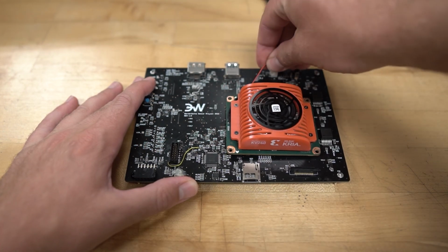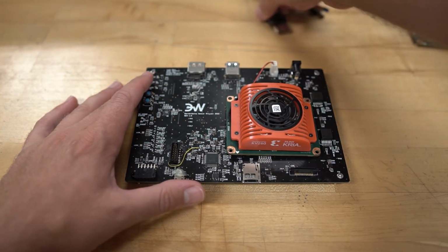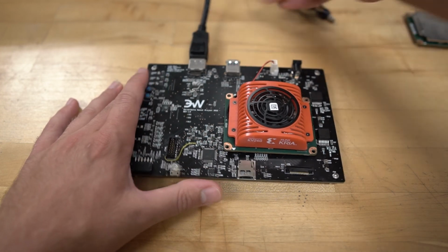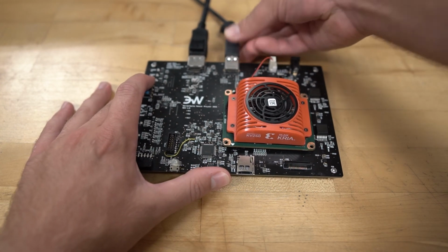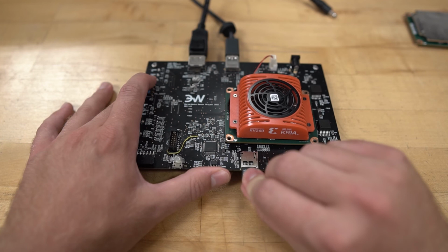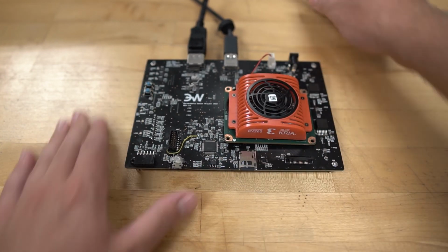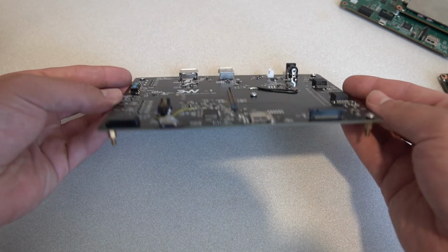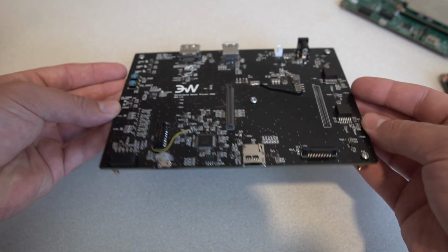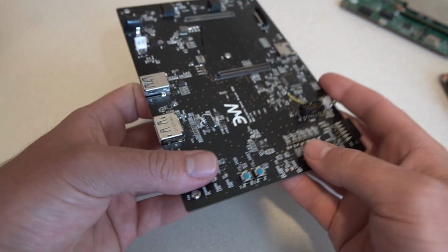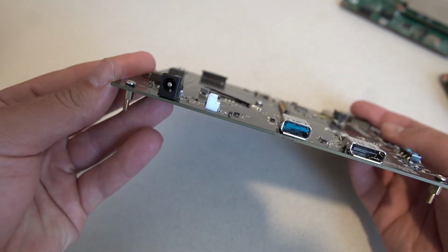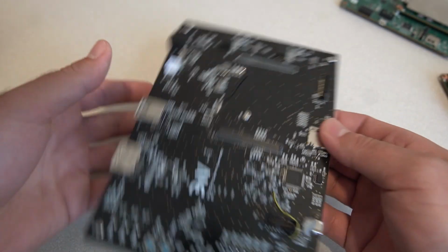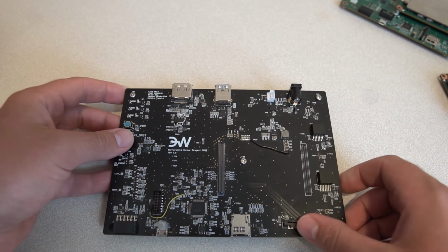On our own custom board here, all that we needed was the main connector here in the middle for our Kria SOM, which plugs right in. And then we have an SD card here on the bottom that's used for booting the board. We have JTAG over here on the side, which is used for debugging. UART on the bottom for actually communicating with the board with our computer. We have power, power for a fan, a USB port, and then a DisplayPort for driving a monitor.